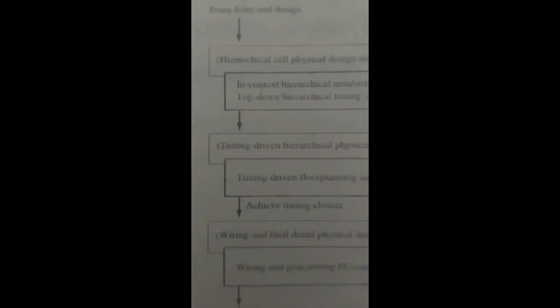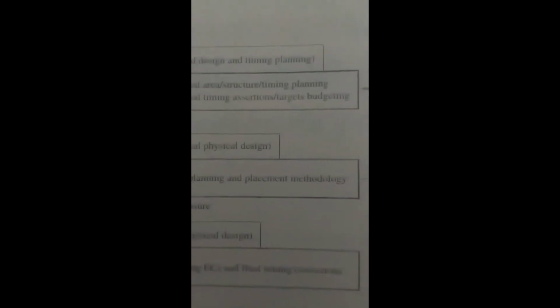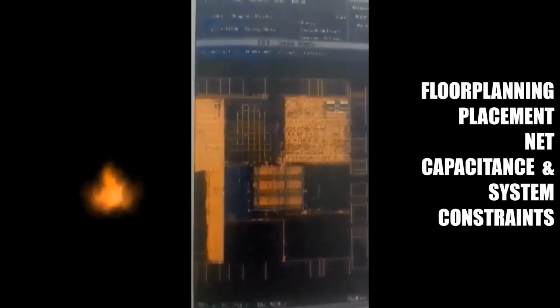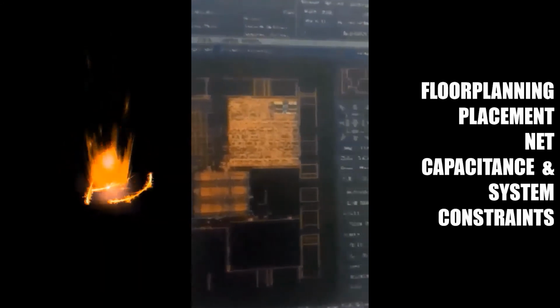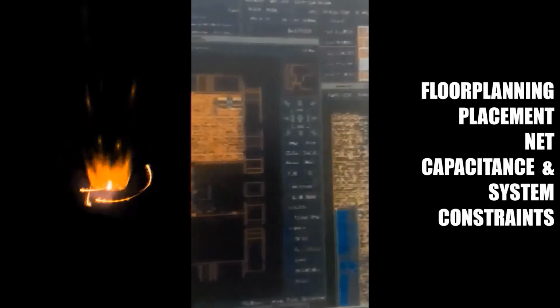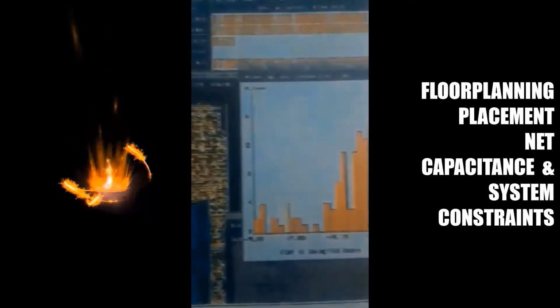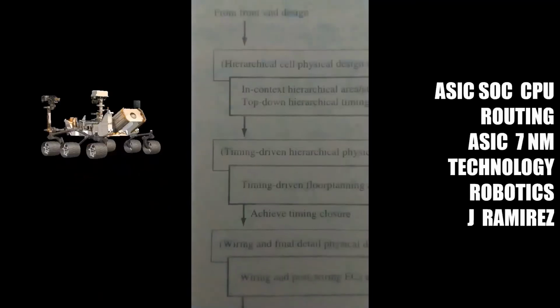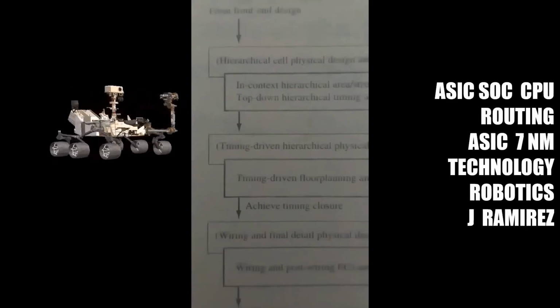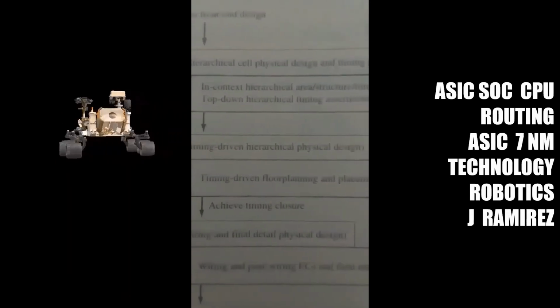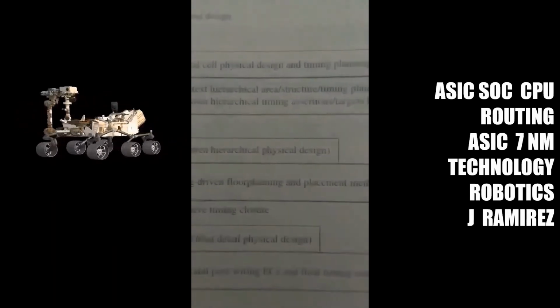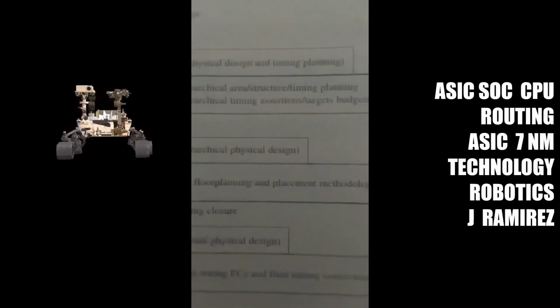They include pre-placement, for planning, specification of circuits to be placed in adjacent locations, net capacitance, and source to sink resistance constraints, and weights for the various components of the scoring function, including net length, congestion, and population balancing.